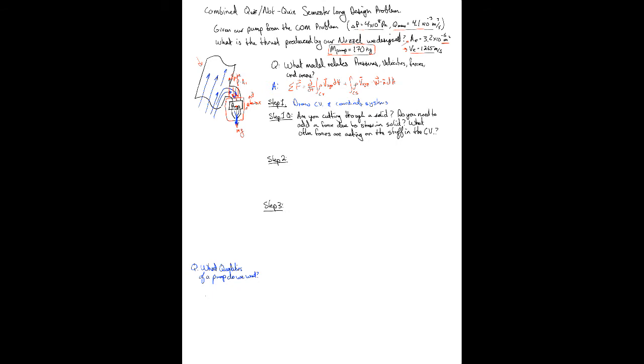So we've picked a direction, which is F pipe, and our pressure, area, and our mg are all in the y direction. So we're going to pick the y direction, obviously. So we're going to write down our equation here, equation 1. We have negative P1 times A1. And remember, it's negative because pressure always acts inward on a control volume, so it's going to be acting down.